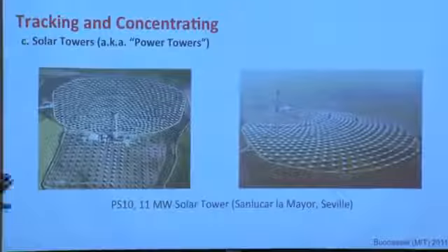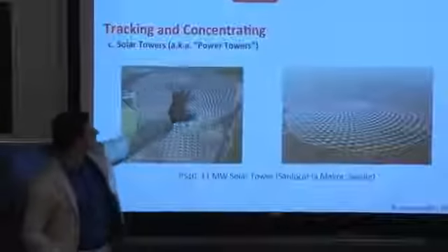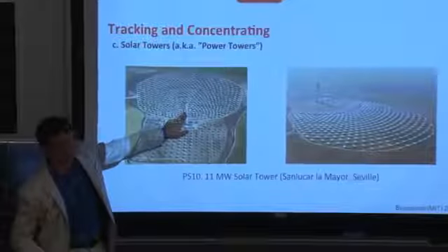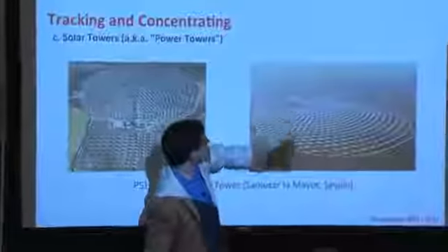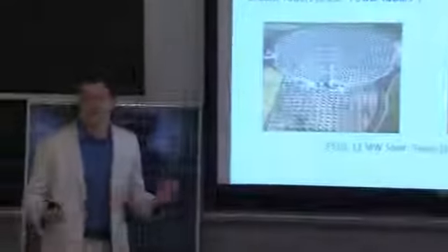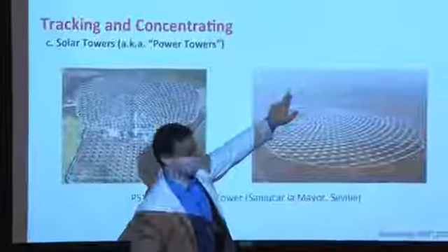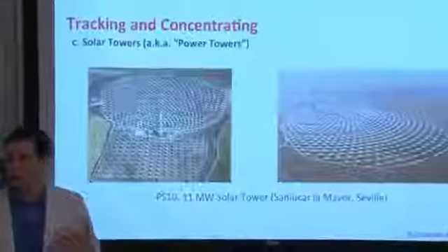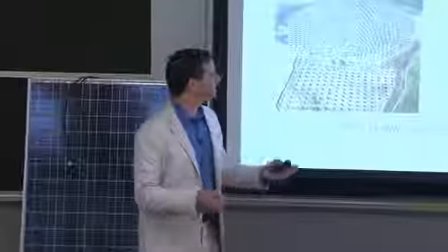And you also have solar power towers. There's some work going on at MIT in this as well with Alex Slocum and others that are using fields of mirrors to concentrate the sunlight into a tiny little spot right here in a big tower. Say, for example, that spot right there. It's dark. It's not in operation. But if it were, the sun would be concentrated into that little spot. It'd be really, really bright, indicative of its very high temperature on the order of a couple thousand Kelvin. And then the sunlight would either be absorbed up here with some molten salt or reflected down underground into a heat reservoir. And that would be your T-high running your engine, right? So your Carnot engine. And then the T-low would be the ambient temperature.